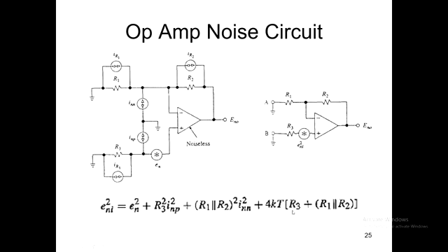which is 4kT times R3. It's that one there. And once again, when you've got two resistors in parallel with each other, you can sum on a mean square basis, and that means that we've got 4kT times R1 parallel R2. It's a mouthful. So you have to square root the R1 parallel R2 then. This one over here, over on the right.